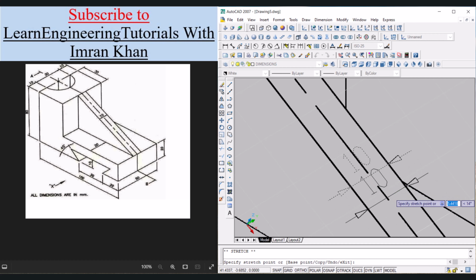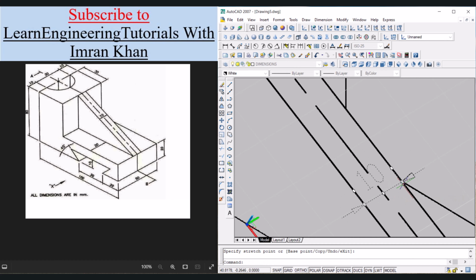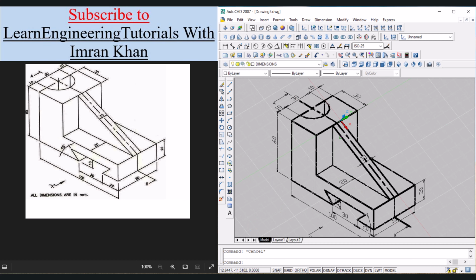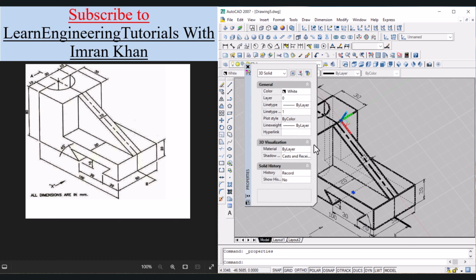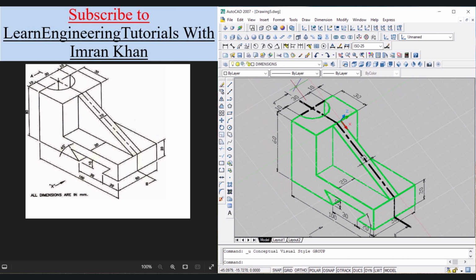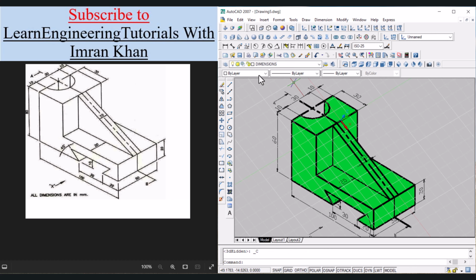So let us place the text and the dimensions over to this point. Click again, bring them a little bit below, press escape. Now the dimensions look okay. If you want to give it color, you have to just double click, and from the color you can select, for example, blue color or yellow color or green color. Click on cross, and now if you go to conceptual view, we can see that the color of the object is changed.